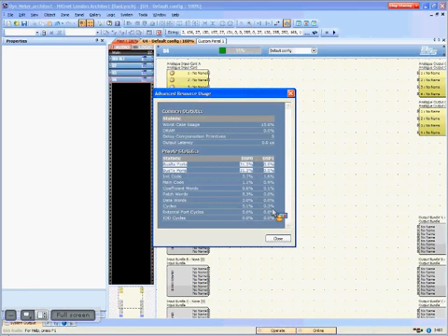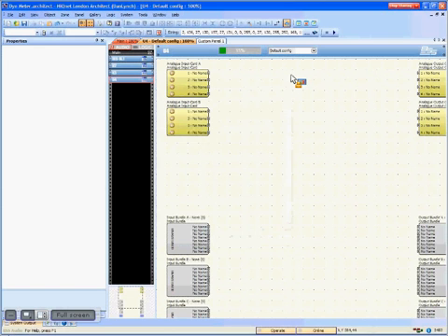The Blue 80 has 32 channels reserved out of 128 for CobraNet. So you end up with only 96 BlueLink channels, whereas the Blue 160 can process a full 128. So that's what that little resource meter, that doesn't always make sense, is trying to tell you.